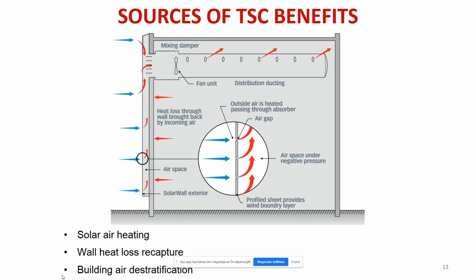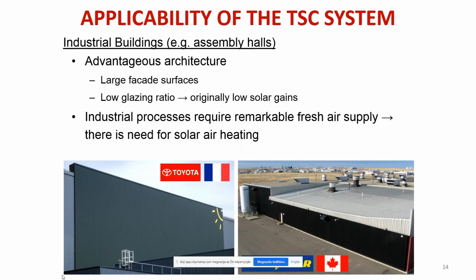One does not like this because in an industrial building, it's the lowest 2 meters that we use for occupancy, and this is why we do not want the heat go out of this zone and accumulate below the ceiling. And once we create an air distribution in a clever way inside of a building, we can mix up this distribution and create a rather more even temperature profile inside of a building.